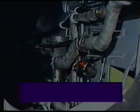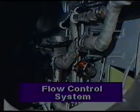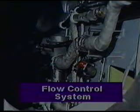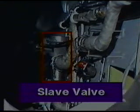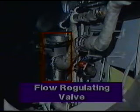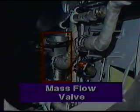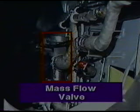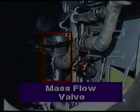The three units installed on the left-hand side of each nacelle to control bleed air are called the flow control system. The larger of these units is sometimes called the slave valve, flow regulating valve, or even the mass flow valve. The name mass flow valve is technically incorrect, but is sometimes still used by mechanics that worked on older Metro aircraft.